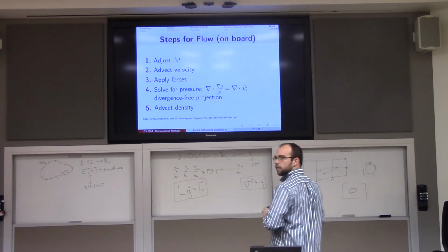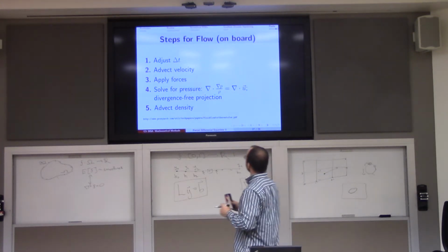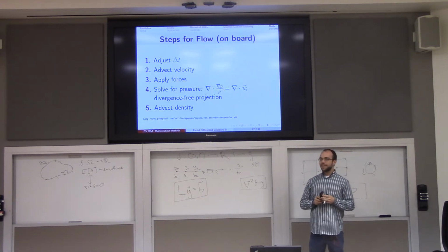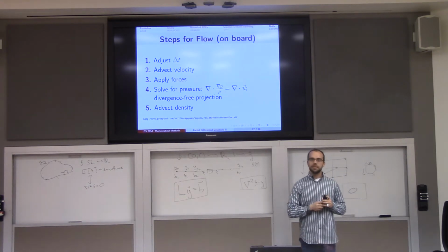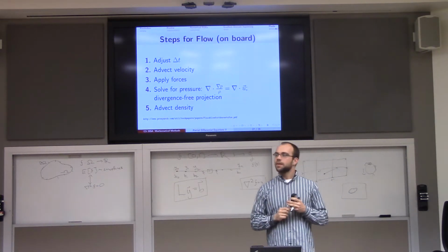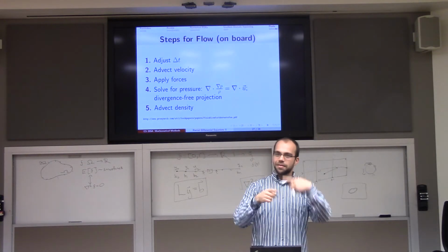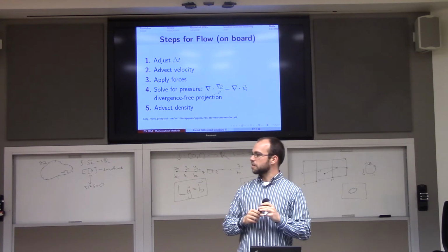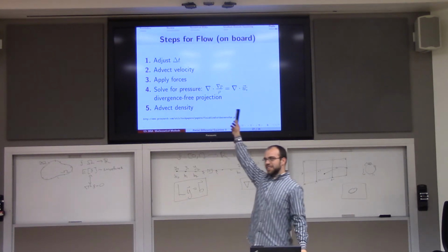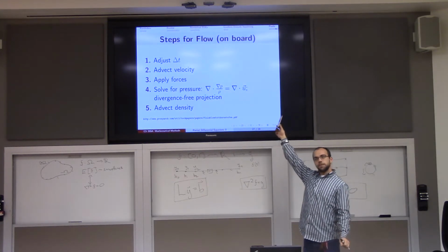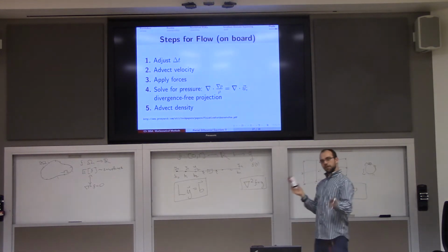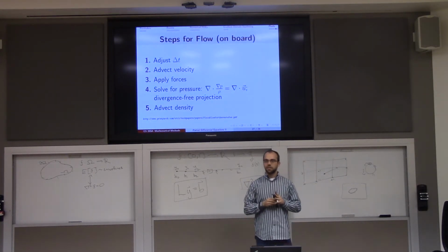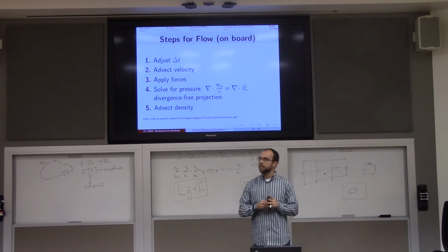So the steps for flow, unfortunately we're low on time. If you want to solve a fluid flow equation, it's actually quite simple to implement using all the tools that we've developed in this class. First, this is sort of an ODE problem, with a time variable, and you look at the dynamics and the velocities you see in space, and choose a time step delta t that you know is going to be stable and consistent. This is particularly important for fluid simulation because depending on whether your fluid is crashing around or splashing or settled, you might have to adjust your time step to resolve that behavior. And that's a very important decision.